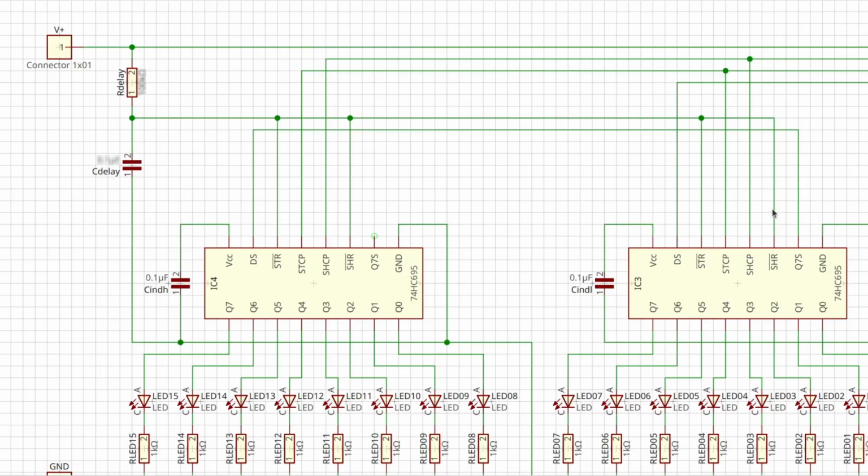So what we really need to do is start with those pins low and then bring them high after some time. And we can do that by connecting all of those pins to an RC circuit, resistor to high and capacitor to ground. Connecting the pins this way means that we're going to reset the shift registers upon startup. So it will start at ground. And after some time, will then be raised high for normal operation.